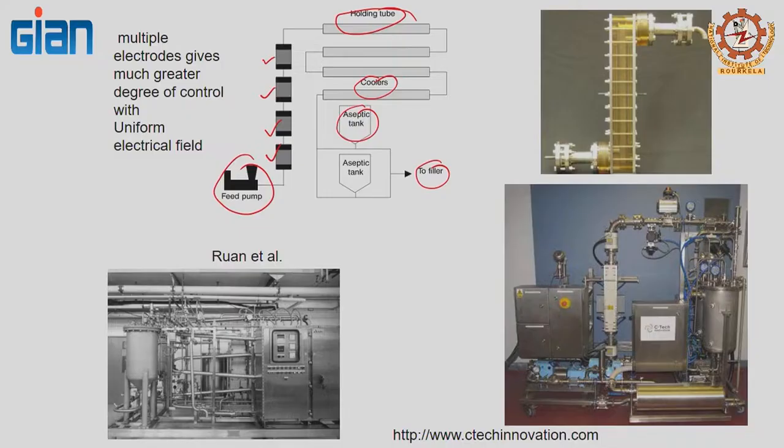So you go to stage 3, and then you increase the temperature further. At that higher temperature, say 75 Celsius, the electrical conductivity becomes higher still. That means the electrical conductivity value and the temperature are coupled with each other. As the temperature increases the electrical conductivity, more current passes, which increases the temperature further, and so on. This is the reason for having a controlled temperature increase. They probably have 4 heaters so that they can modulate the temperature increase in a controlled manner.